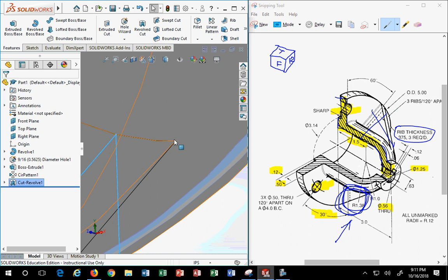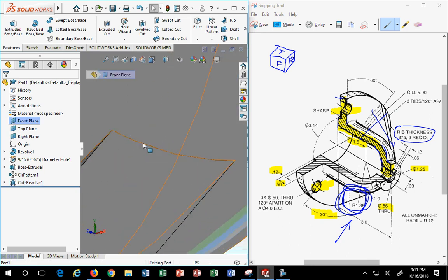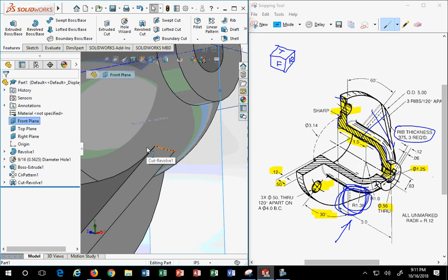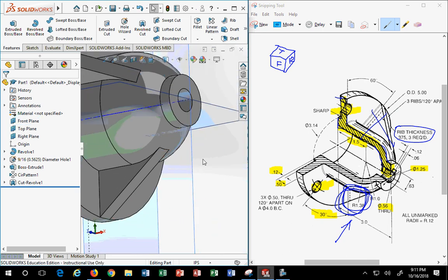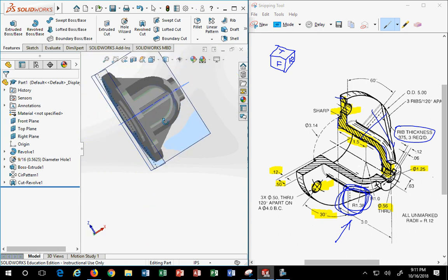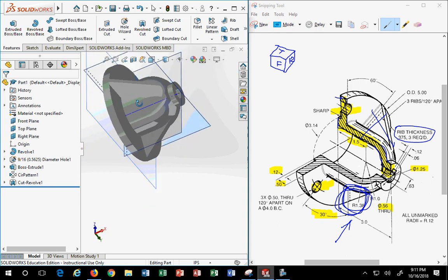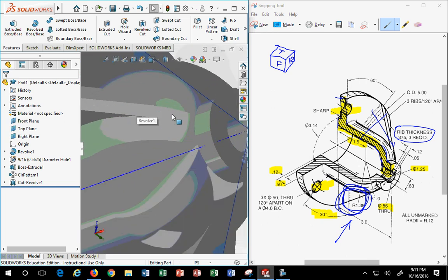What remains is the line that represents where those two objects connect, because anywhere there's a connection point, the software does that. But if you want to see what it really looks like, you change to shaded mode, and then you see that there is really no line there, because that's a pure tangency point.